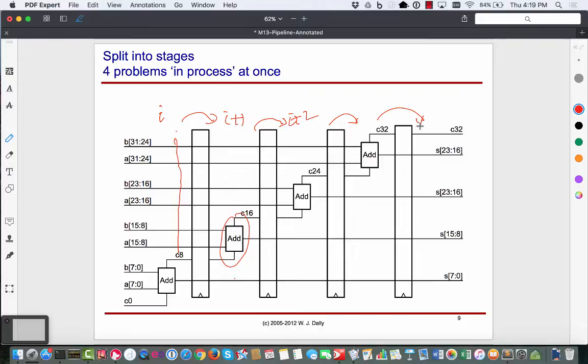So what decides the clock tick size? Let's go back to the past couple of lectures. What dictates how fast the hardware can run? The time for each adder to finish. So combinational delay, the largest combinational delay from flip-flop to flip-flop, right?